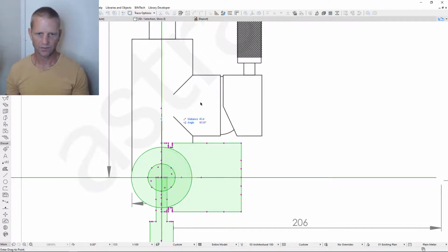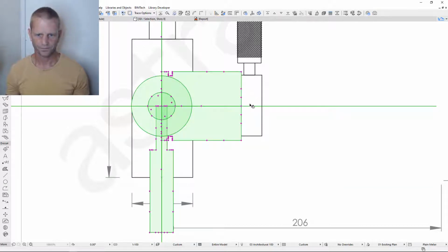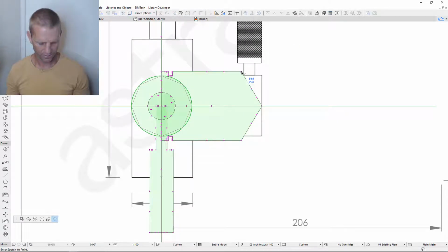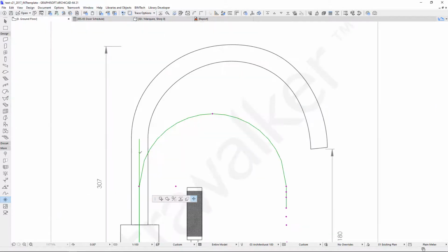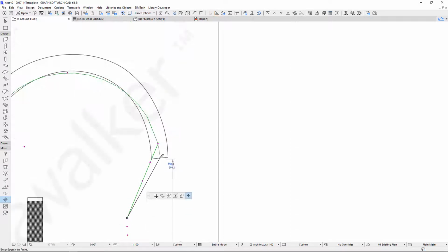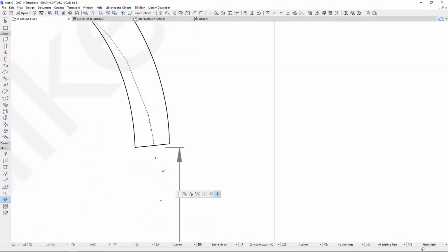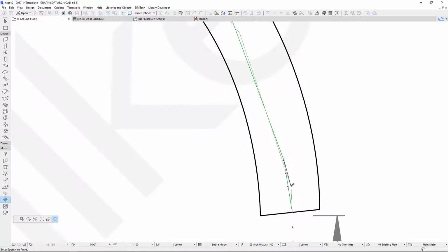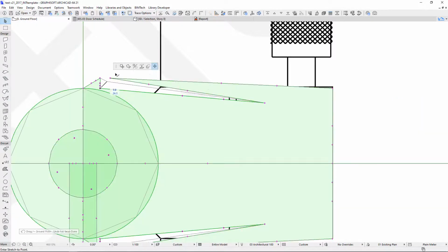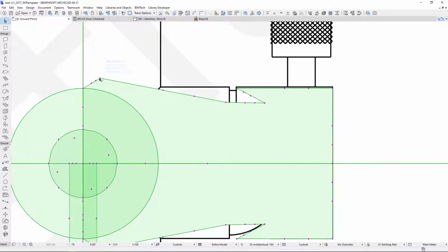So let's drag this element up to what we think is the center point. It looks like 52. So let's stick it at 52. Drag this element out to here, which is 73. We know this is a 44 diameter because it's the same as the other. So this should be 73 tab 22. This in here should be at 22. And then we can move this little notch up to the position of our notch.